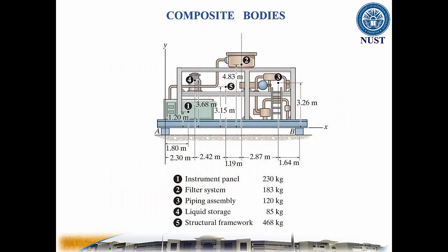The compressor is assembled with many individual components. In order to design the ground support structures, the reactions at blocks A and B have to be found. To do this easily, it is important to determine the location of the compressor's center of gravity. If we know the weight and center of gravity of individual components, we need a simple way to determine the location of the center of gravity of the assembled unit.